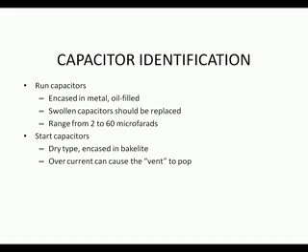Now, with the newer digital meters, use your capacitance scale. The reading will be in microfarads. Put the two leads on the capacitor after you've shorted out the two terminals and removed it from the circuit. The reading will give you the actual capacitance in microfarads. It should be within 5% of what the capacitor rating is.